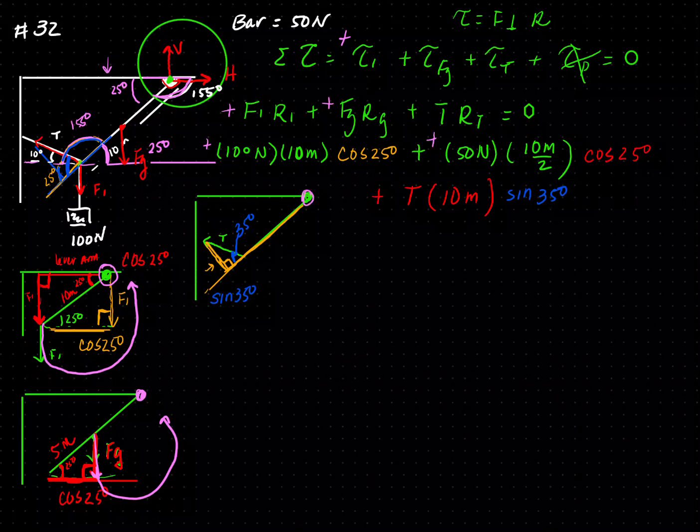On this one, this is my pivot point. If I pull my bar this way, it's going to rotate clockwise. So my tension here is going to be negative. So T becomes 198 newtons. So now I'm going to write a sum of Fx equation.